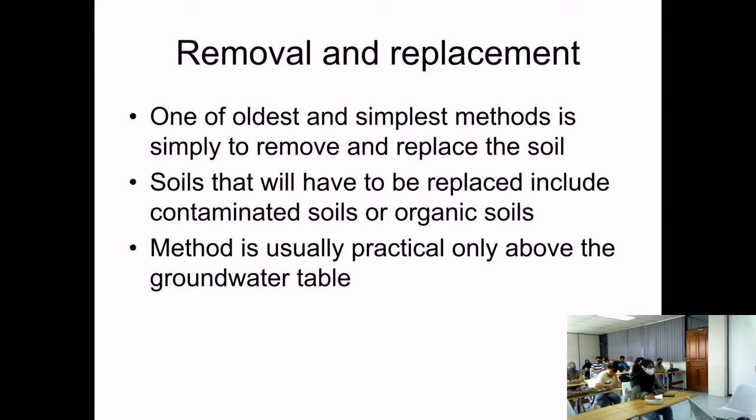But the only limitation is that this method is only practical above the groundwater table. If the very bad soil is below the groundwater table, it is very difficult to remove it. When it's underwater, it's very difficult to remove. It's only practical for soil above the water table. So as soon as it reaches the water, this method of removal and replacement is not efficient.